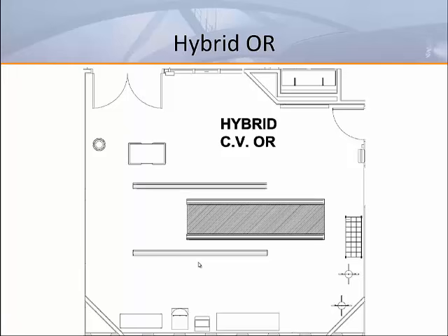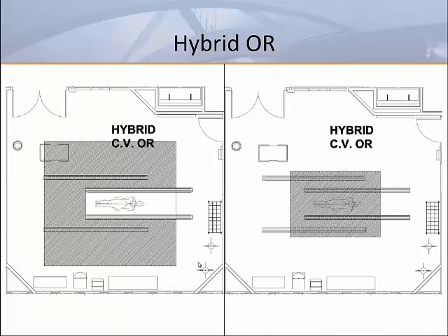This restriction makes it much more complicated to comply with the array size requirements from Standard 170. The image on the left highlights the region that must be covered by diffusers to meet the minimum airflow requirements and velocity requirements of Standard 170. Conversely, the image on the right shows the minimum array size if the restriction for no air distribution devices in between those center rails applies, and you can see the drastic difference that it makes between the two area requirements.